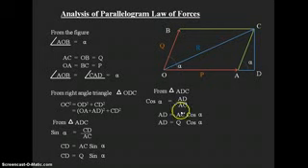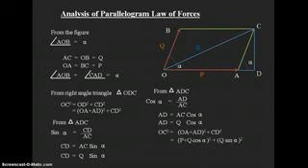So here observe again, we got CD, and we got AD, and we know OA. Here OA is P, AD we got as Q cos alpha, and CD we got as Q sin alpha. So substitute all these values in this OC square formula. OC square is equal to, as I have written, OA plus AD whole square plus CD square. Substituting the values, that is P plus Q cos alpha whole square plus Q sin alpha square.